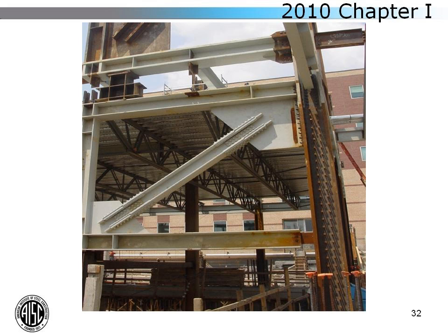Now when I was designing these composite columns, I had to determine what the shear strength was for these studs, the various transverse tie configurations, and there actually wasn't a lot of guidance given within the previous specification when it came to those topics. So I started asking some questions, and one thing led to another, and now 8 years later I'm giving a presentation on it. But I'm happy to say that due to the hard work of the remainder of the composite committee, along with the AISC staff, the 2010 specification addresses all of these questions very nicely.